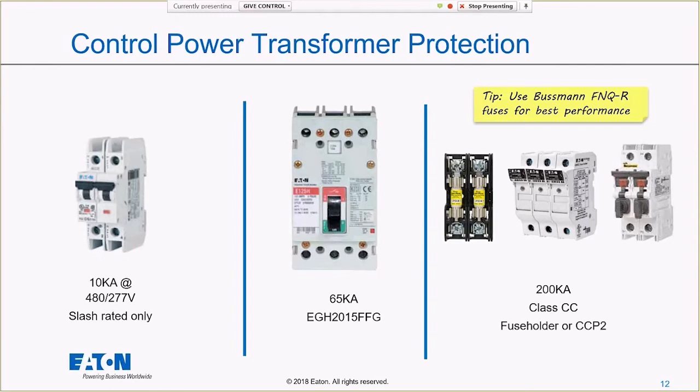A lot of times you only need 6 or 9. So, how much protection are you actually getting out of a 15 amp breaker there? And of course, you pay more for the higher interrupting ratings, and to get it in that molded case frame instead. So it's technically an option. Probably makes more sense when you've got a whole lot larger power supplies or control transformers, just because of that 15 amp rating.